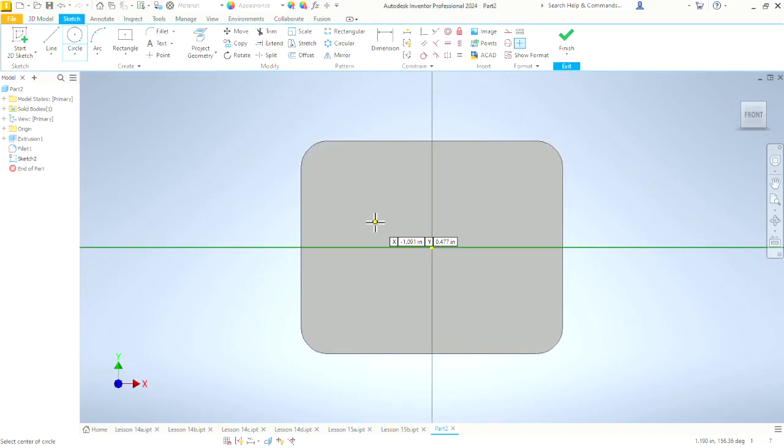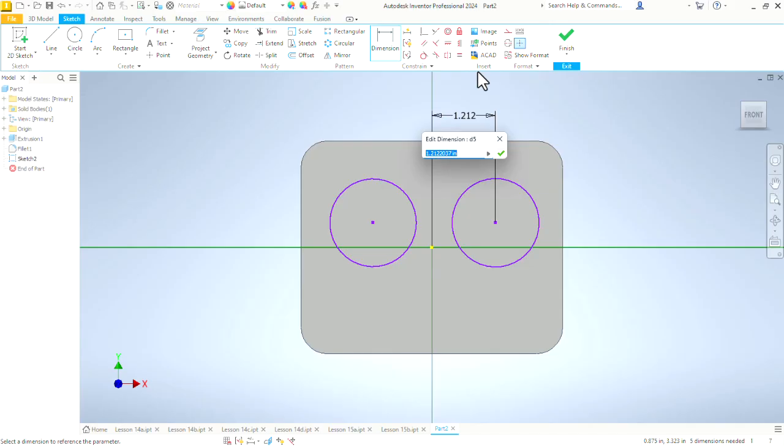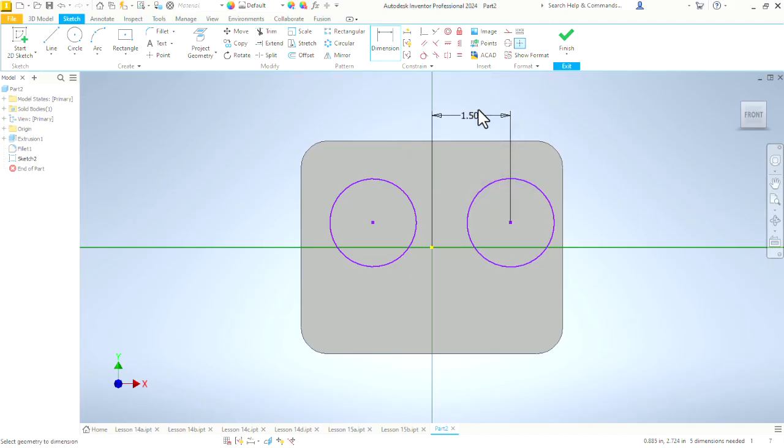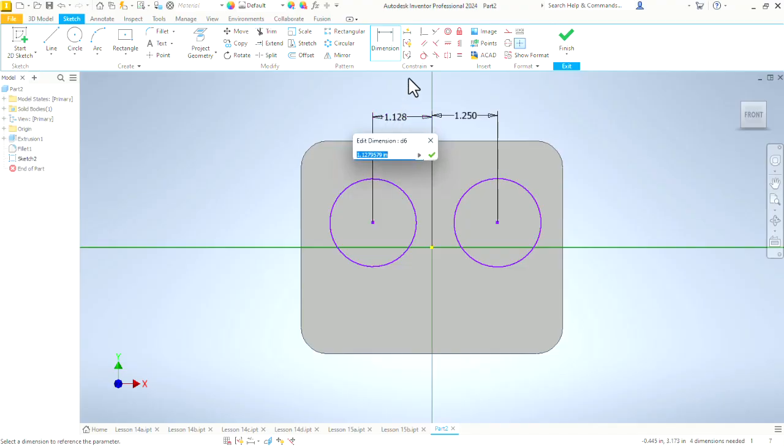Now we will create a new sketch on the front of this part. Let's put a couple of circles up here. It doesn't matter exactly where they are, but we'll throw on two circles. This is going to end up looking something like maybe a carburetor adapter plate. If you're familiar with what that would look like, it's got holes on one side that join with holes on the other side and create a tunnel through the part that will align holes that are in two separate locations.